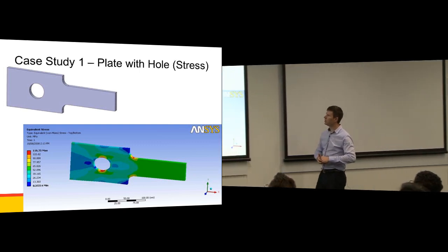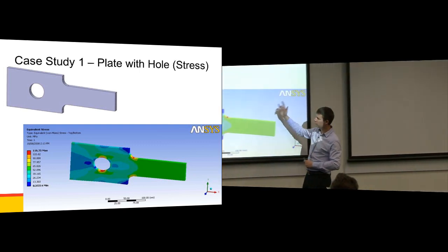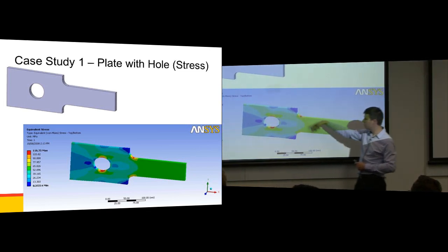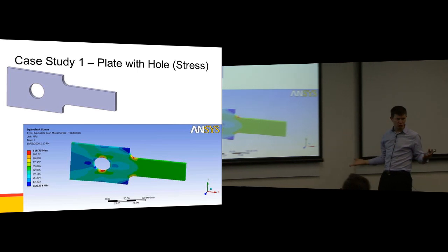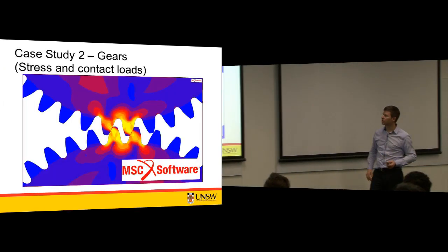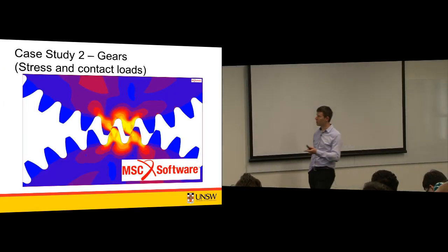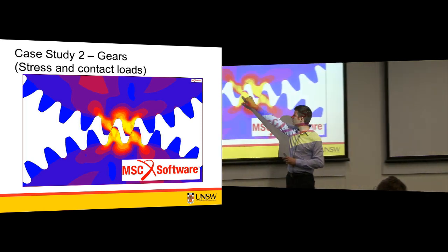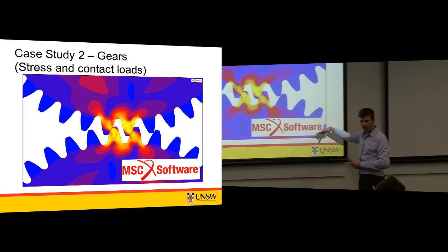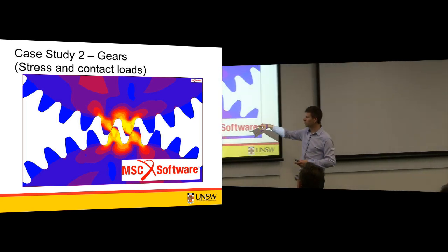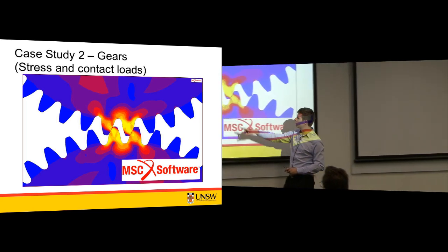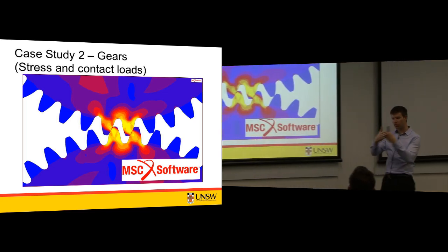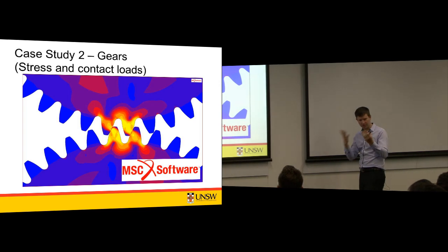We'll flip through these. So this is ANSYS, strange enough. We said you'd want to see stress concentrations around a hole and at fillets and chamfers, and you do. It accurately simulates those things. Contact is something that we'll look at as well. So you'd want to do contact loads and also internal stresses. This is really tough to do numerically because you've got 2 gear teeth in contact, and defining those so they're actually in contact is quite difficult.